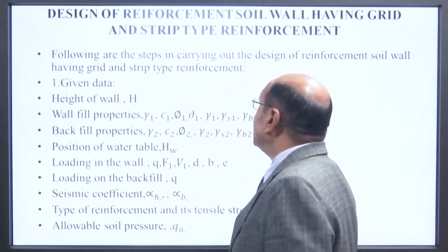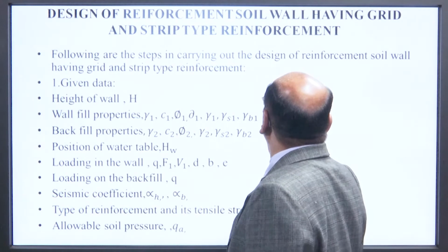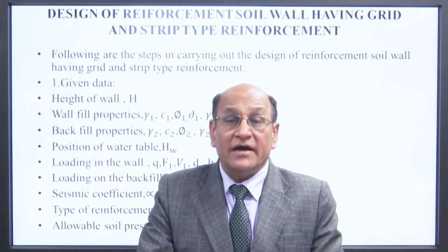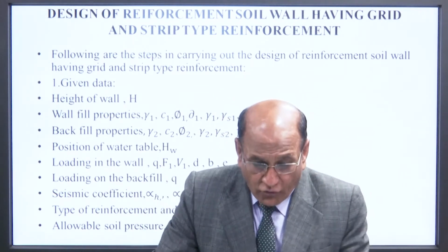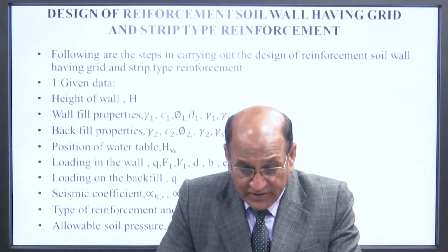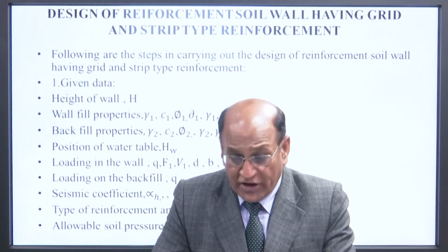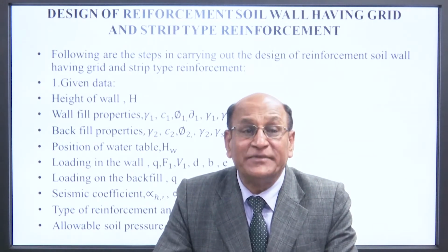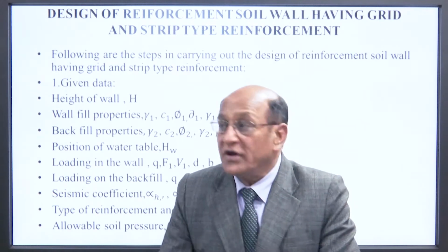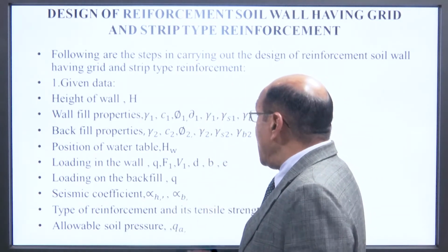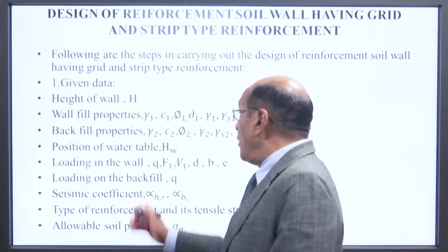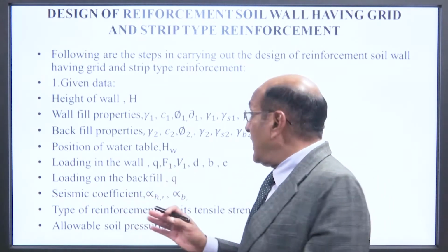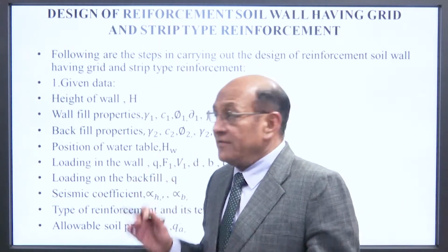So now come to the design of a reinforced soil wall having grid and strip type reinforcement. Following are the steps in carrying out the design. The given data will be the height of the wall, that is H, and the wall fill between wall and the backfill.